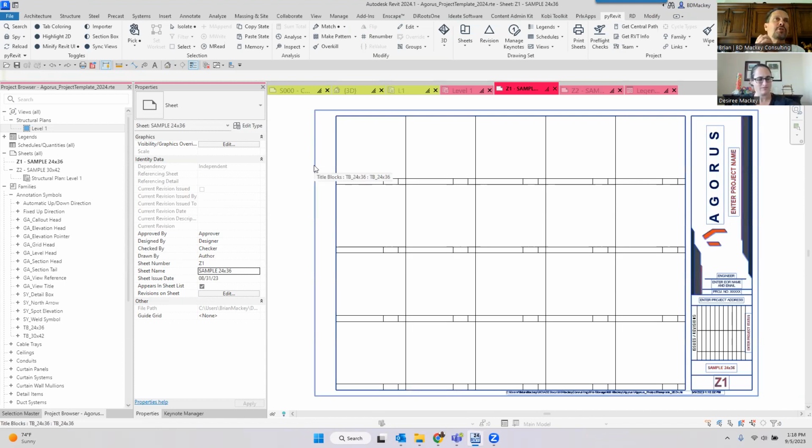So the question came up: shared coordinates, how to get them, how to use them, etc. My head is spinning. I do shared coordinates differently than a lot of people. Often I'm coming in and getting a DWG from an engineer. Whoever is the lead on the project, in my mind, it's their responsibility to start setting up the shared coordinates. If you're one of the other people in the project, not prime, if you're the MEP engineer, structural engineer, or whoever's not prime, then theoretically, all you should have to do is acquire coordinates from the prime's model.